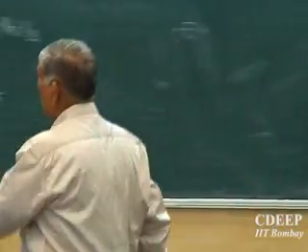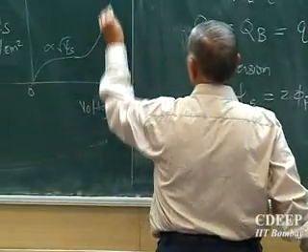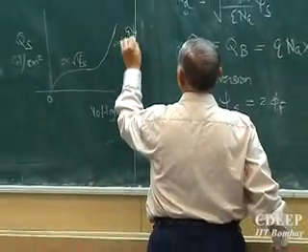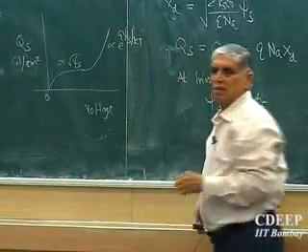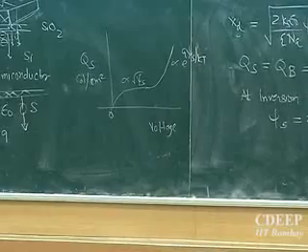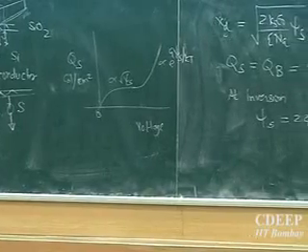Okay, the first part therefore, as he is interested to know, till psi s goes from phi f to 2 phi f, close to phi f we say we are in weak inversion. Weak means very small number of electrons are made available to us. Because the figure says, after this, it shows proportional to e to the power q psi s by KT. So as you cross this, inversion charge will come from the inversion layer itself, electrons, and you don't need any depletion charge to come.